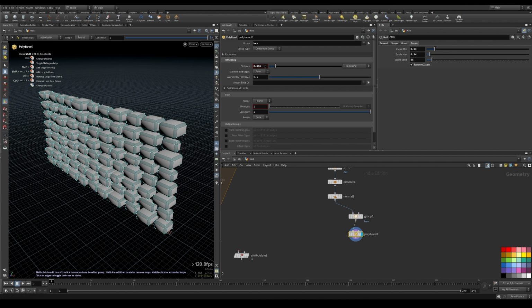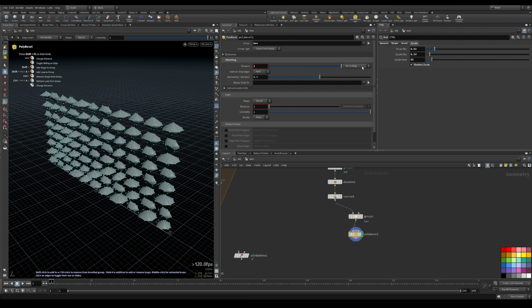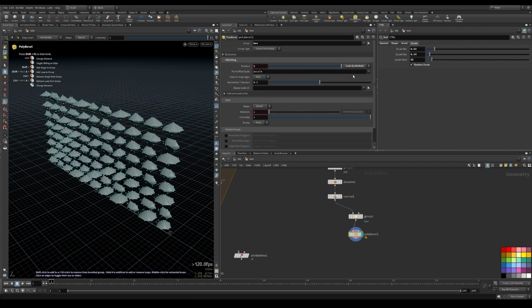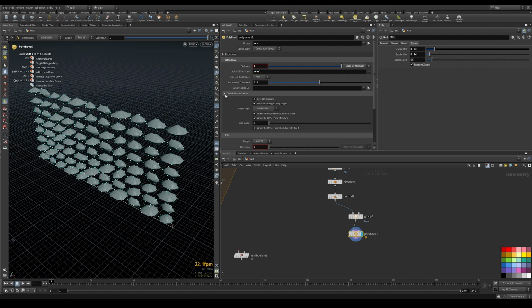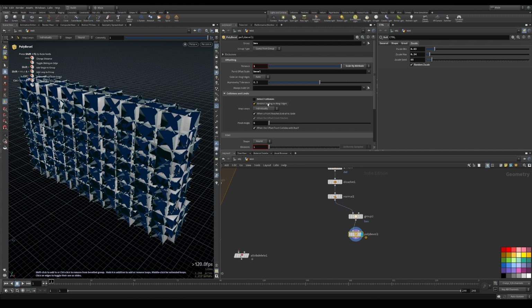So just like for the extrusion, we want to set the value to 1 and activate the scaling by attribute. By default, it's driven by the p-scale, but we will create an attribute called bevel. So write bevel here. And here I want to disable these two voices. I noticed during my test it was better with these two disabled, because sometimes the bevel got blocked with the random values.